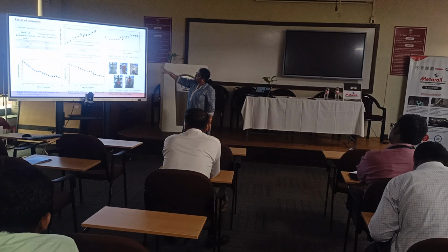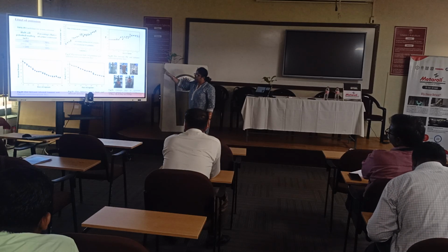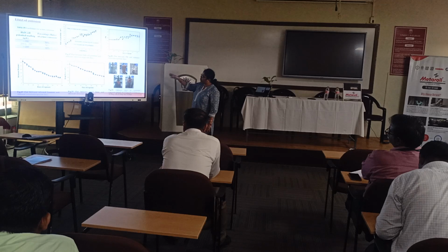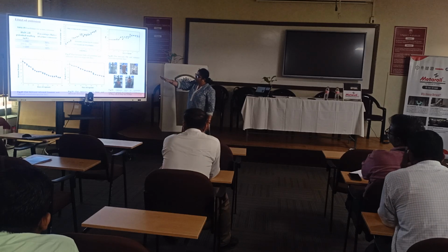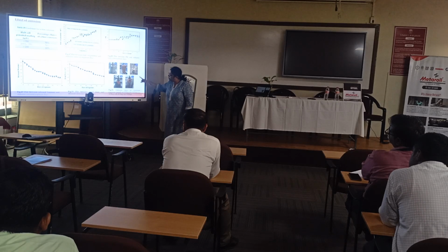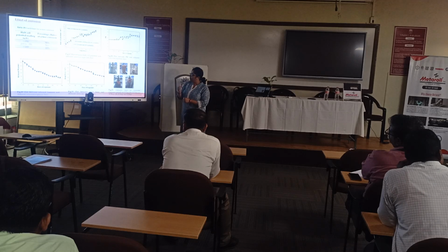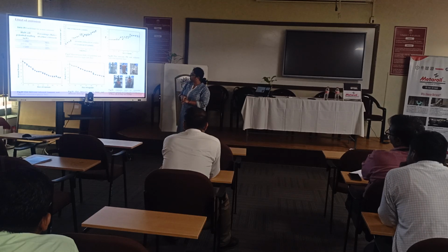So at maximum, with 90 days of exposure, 80% of specimens are in corroded form. We see a variation of the exposure in terms of compressive strength as a rebound power, and bond strength as a pull-out test, and you see how corrosion progresses across 90 days of exposure for bond while it is being immersed in accelerated corrosion.